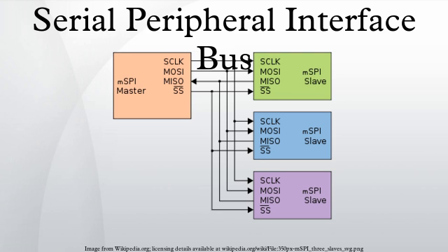Microwire, often spelled μWire, is essentially a predecessor of SPI and a trademark of National Semiconductor. It's a strict subset of SPI, half-duplex, and using SPI mode 0. Microwire chips tend to need slower clock rates than newer SPI versions, perhaps 2 MHz versus 20 MHz.